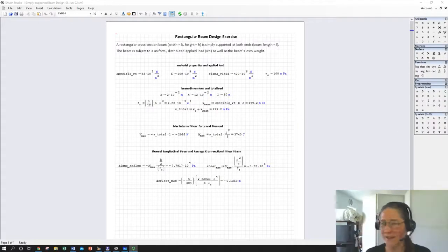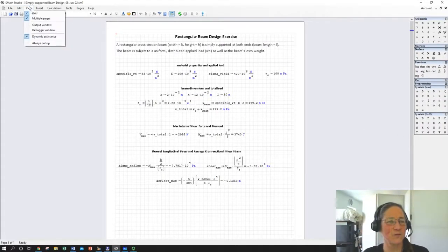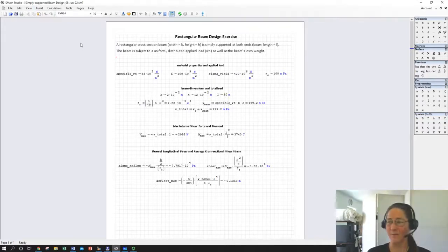At this point, hopefully you are seeing a reasonable view of an SMath MathCAD spreadsheet, where I took pretty much all of the equations for beam dimensions, supports, loading, material properties, and our calculated expressions for moment of inertia, longitudinal stress, max shear force, max moment, internal moment and shear, max shear stress and max deflection from the tablet, and put in expressions which could be varied at will.